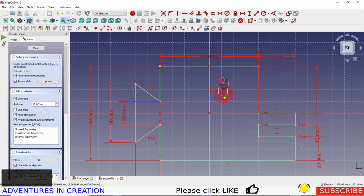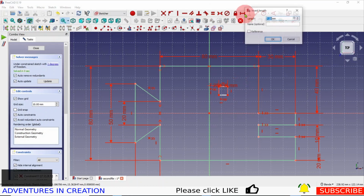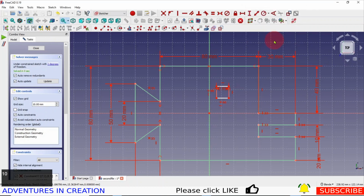And then I can dimension this line as 10 and drop him down there. And because I said this line and this line are equal, and it has vertical and horizontal constraints, that's all you need to lock that square in.